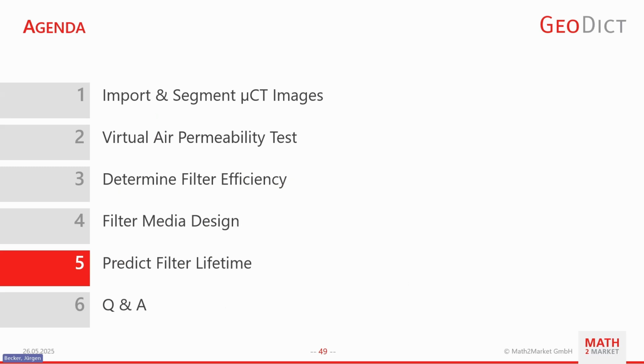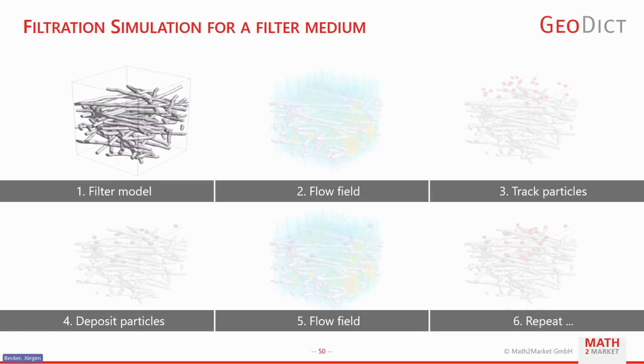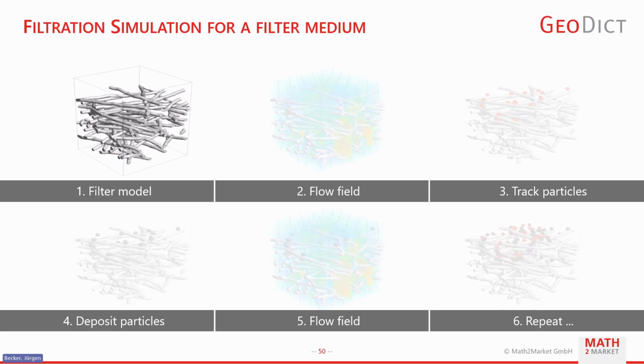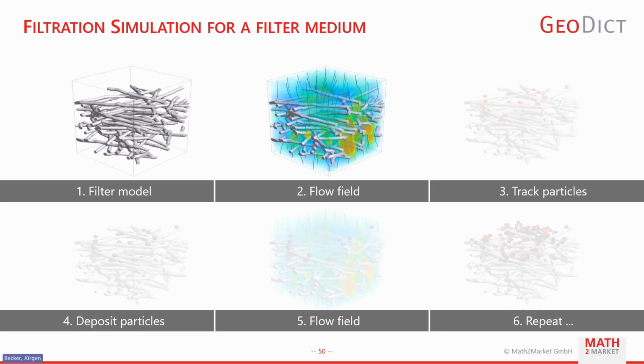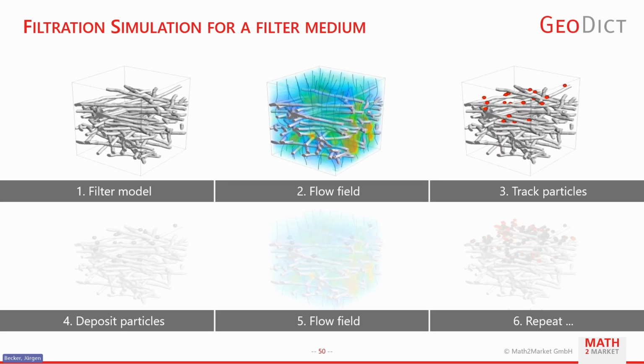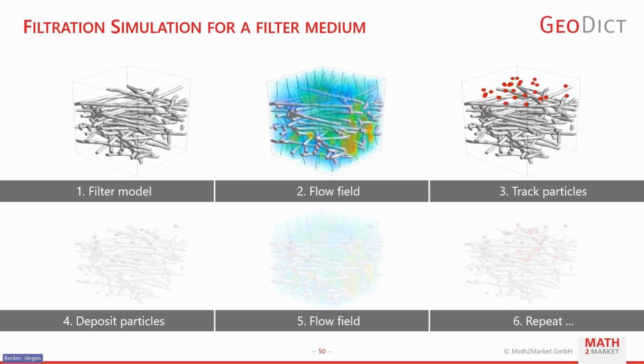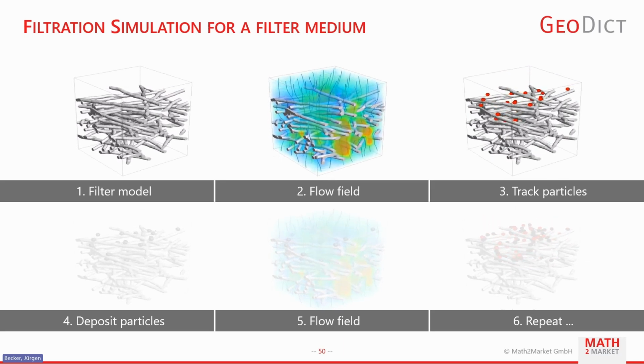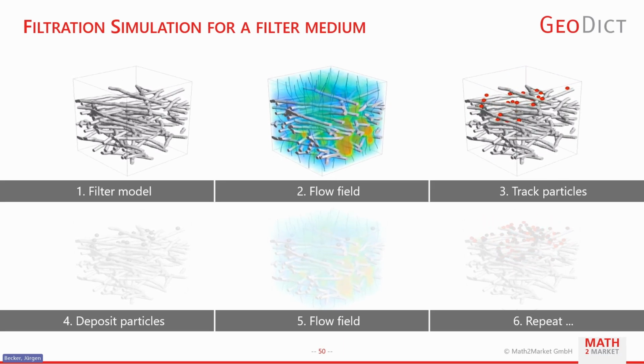So now, very briefly, a short look-out on filter lifetime. To simulate filter lifetime, we can start exactly as for the filter efficiency, the first 3 steps. So we have the model, GeoDict computes the flow and tracks the particles. But this is just the initial set of particles.